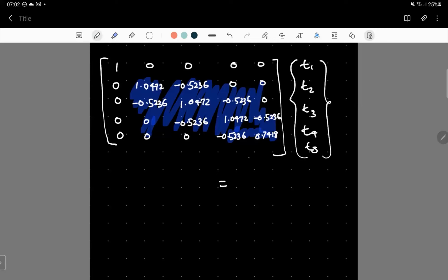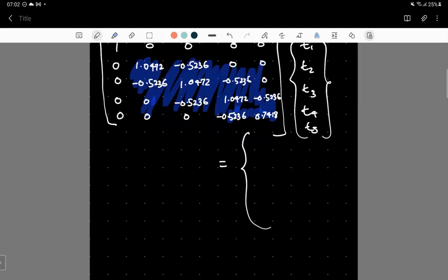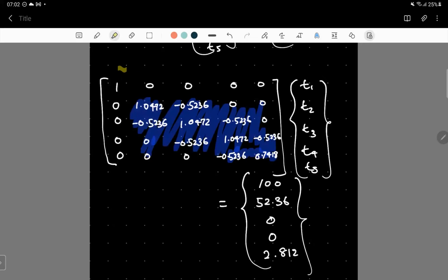Now, when we consider the force matrix, I will write it down and explain. The first term we set to 100. Let me highlight the terms which are changed now: this term, this term, and of course this term. These are already changed in the modified set of equations. So we modify the stiffness or conduction matrix, and of course the corresponding force matrix.